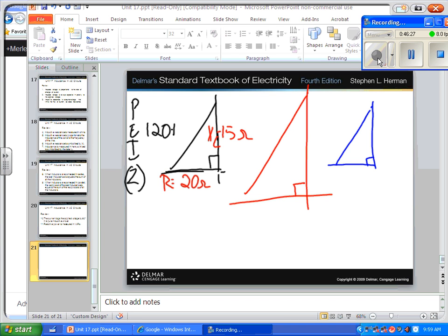From that information, remember our 2 pi FL? We could find how many henries this coil has, couldn't we? We'd have to back into it, right? We'd have to say that 15 is equal to 377 times L. So, in other words, 15 divided by 377 gives us the number of henries, yes? All right, so we're off to a jump.